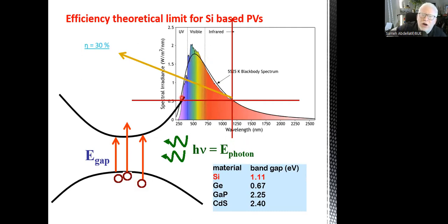And this is one of the main reasons why solar cells become heated under operation. Maybe later on, in our next chapter, considering a solar cell module, we are going to consider what's called the normal operating cell temperature, or the NOCT, which is usually 10 to 20 degrees higher than the working temperature.